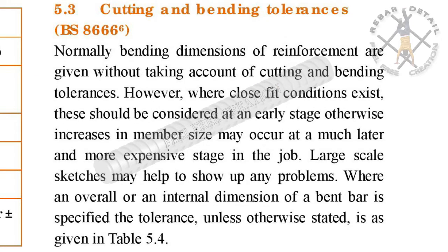Cutting and bending tolerances. Normally bending dimensions of reinforcement are given without taking account of cutting and bending tolerances. However, where close-fit conditions exist, these should be considered at an early stage, otherwise increases in member size may occur at a much later and more expensive stage in the job. Large-scale sketches may help to show up any problems.